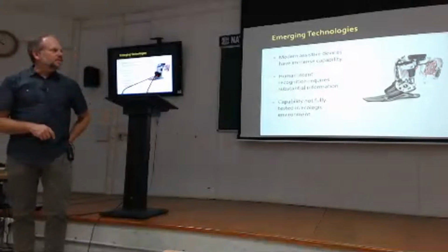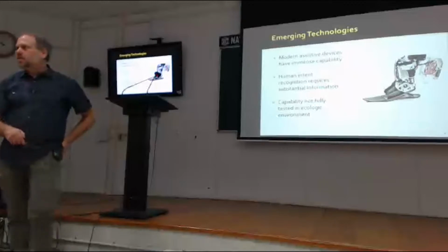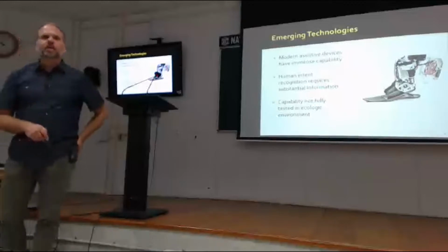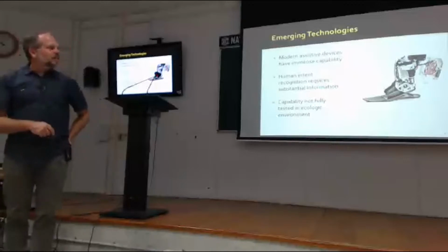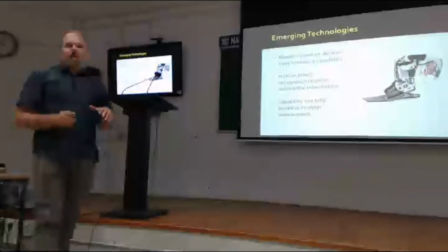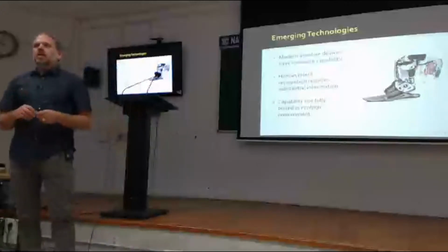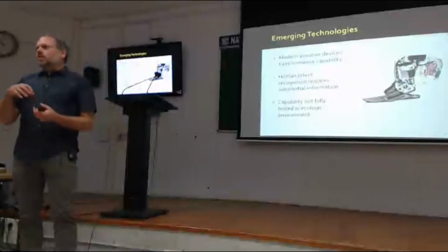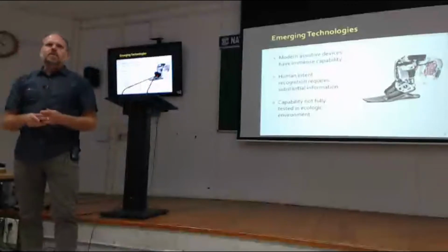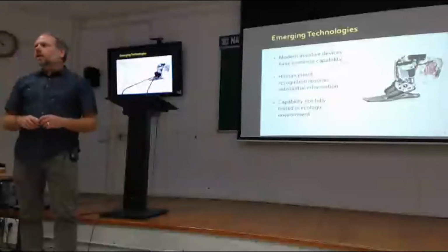And essentially, this is something where you can walk on it passively, the same foot design as the previous shown passive element. But inside of this is also a spring element and a motor in series. And so you can compress some energy into that spring at heel strike, and then you can also drive back through that spring, in series with that spring, almost like you would with your Achilles tendon with the muscular contraction, to drive the heel off the ground and drive the foot into the ground to propel yourself off.